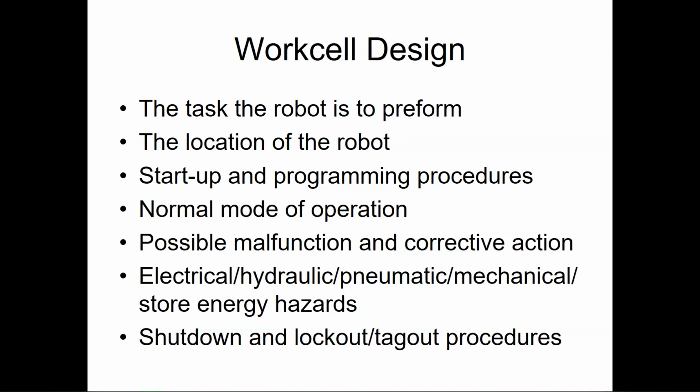Lockout means you have a physical lock, like a gym lock or something like that, a keyed lock of some sort that makes sure that the machine cannot be turned on while you are in the cell or when you're in the area proximate to it and doing any work on it. Tagout can be used with lockout, but it is not lockout. Tagout is something you only should do by itself if and when the machine itself cannot be locked out. You tag it out and let everybody know that is why it is tagged out.